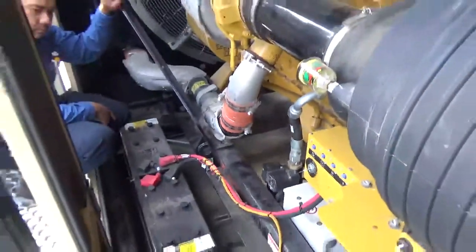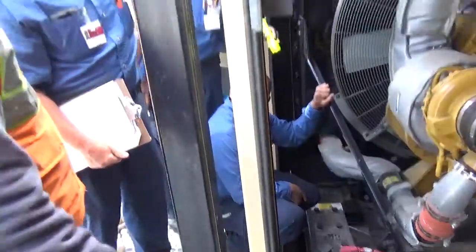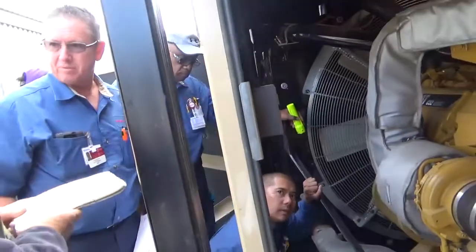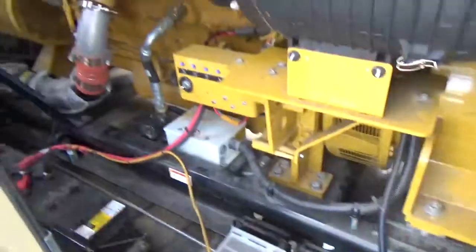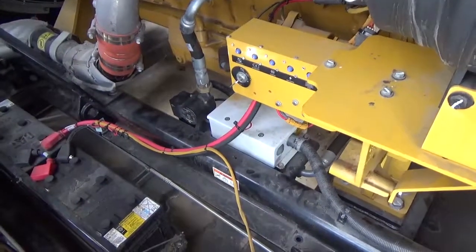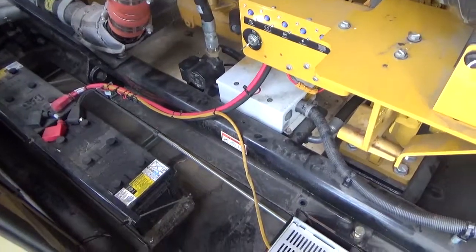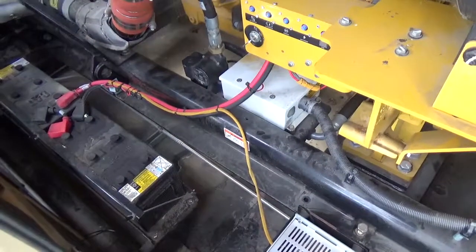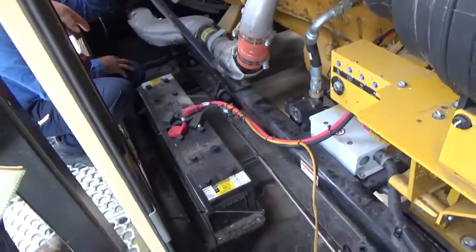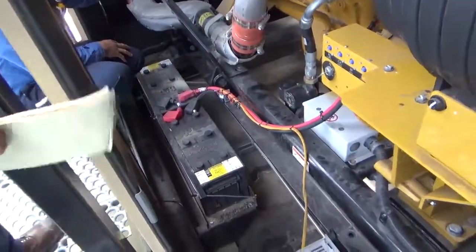If you want to disconnect your batteries, you have to remember to turn the power off to the battery charger. You don't ever want to disconnect the batteries with the battery charger turned on. In theory, you can turn the key off and leave the battery charger on, and you won't do any damage because the DC is coming straight over to here. But when you change batteries, or if you want to double secure and you don't want any DC, you need to find the breaker to turn off the battery charger.